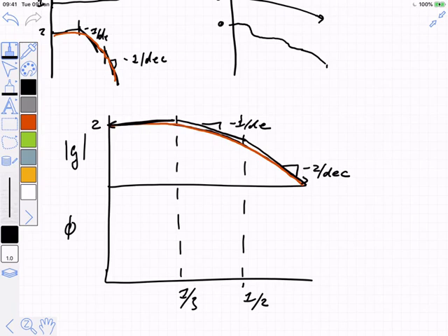We got the asymptotic low frequency behavior by taking the limit as s goes to 0, and the asymptotic high frequency behavior by taking the limit as omega goes to infinity. So we trust those points much more than any of the other points. And so we know that at approximately -90 degrees, there's an inflection point there, there's another one there, and then this goes down all the way.